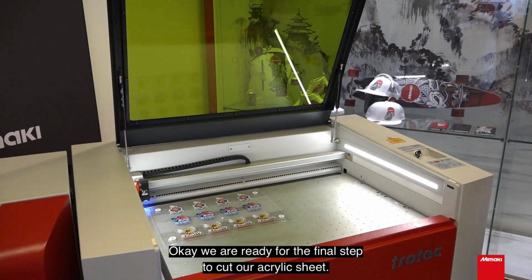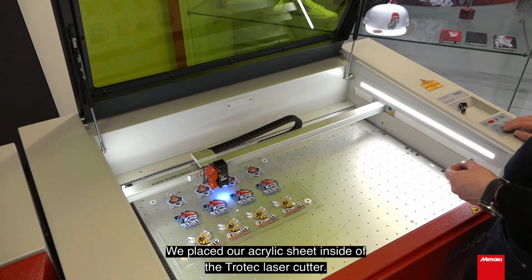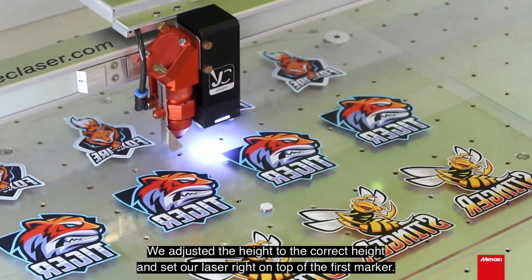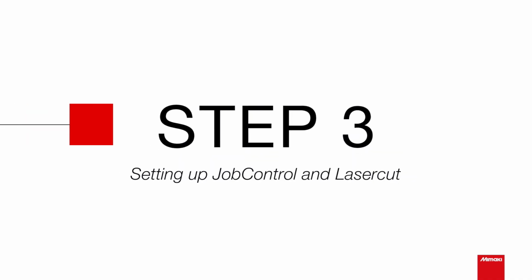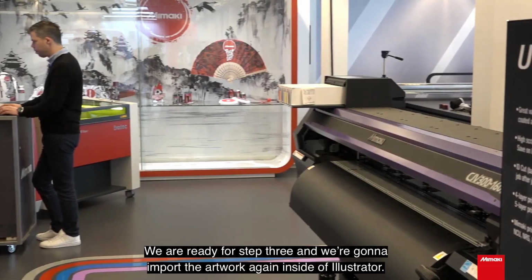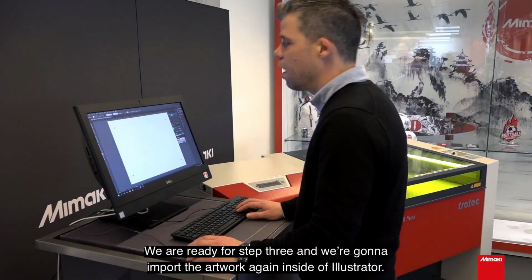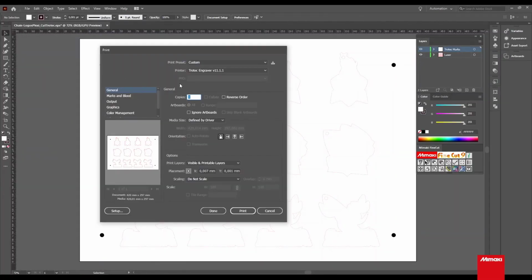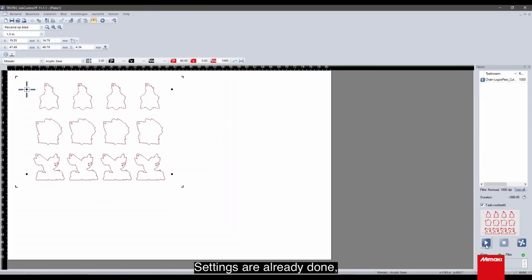Okay, we're ready for the final step to cut our acrylic sheet. We placed our acrylic sheet inside of the Trotec laser cutter. We adjusted the height to the correct height and set our laser right on top of the first marker. We're ready for step 3, and we're going to import the artwork again inside of Illustrator. Settings are already done, so we're good to go.